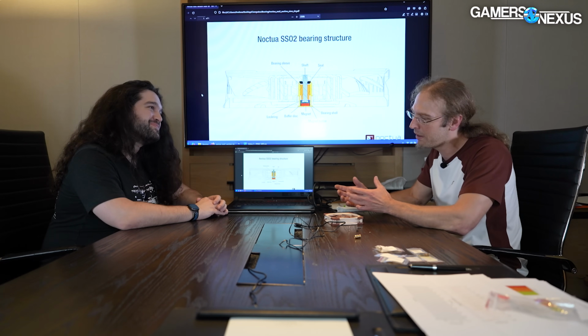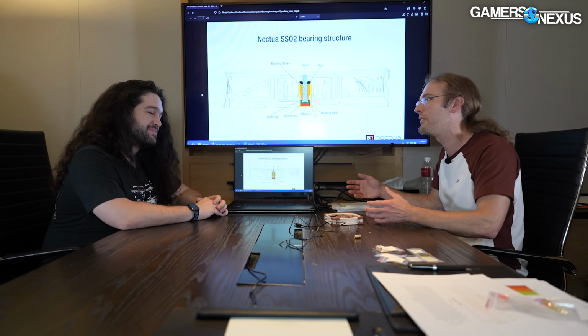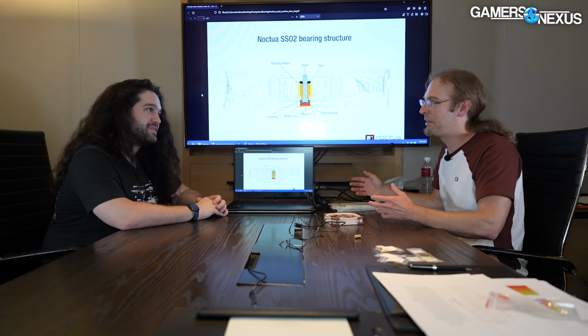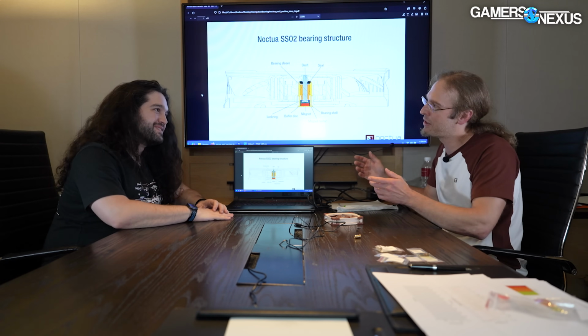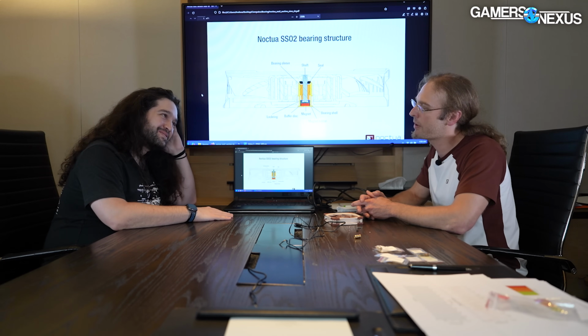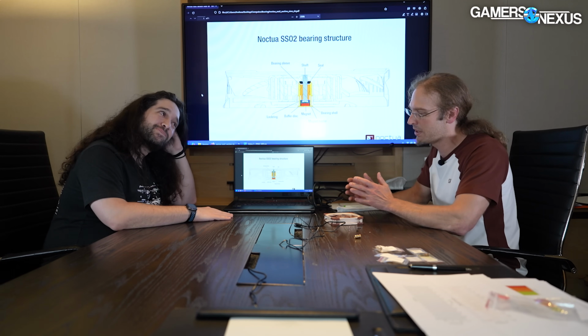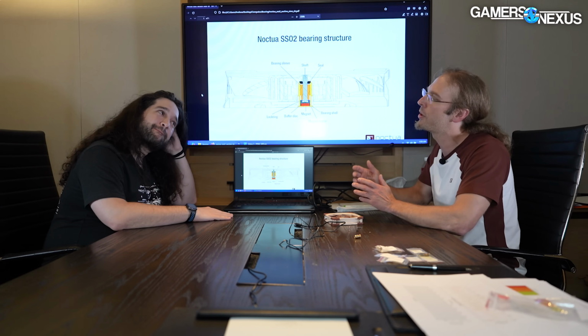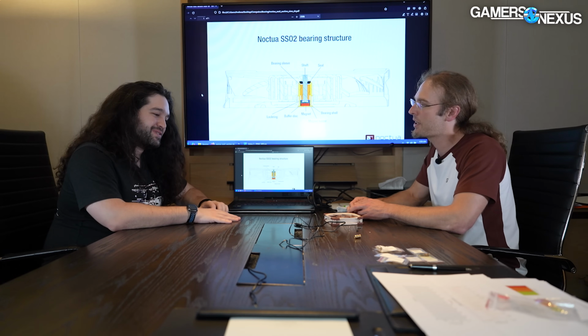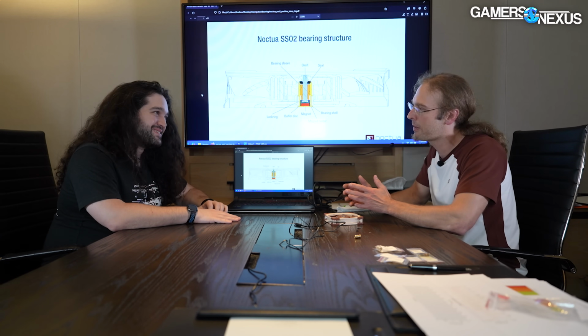Like with any data you use to extrapolate, the further you go, the more uncertain the results will become. And this is why we still stick to this more than 150,000 hours specification, because this is something we're comfortable with. And we now have actually fans running for 17-18 years and knowing that they are running fine. But just going beyond that in specification seems a bit questionable.